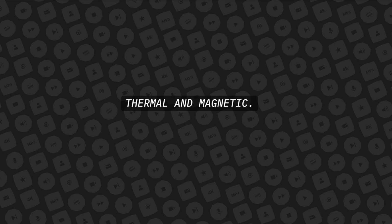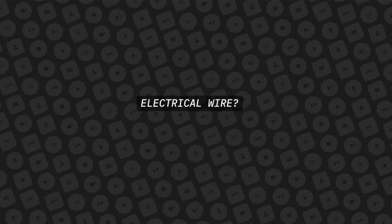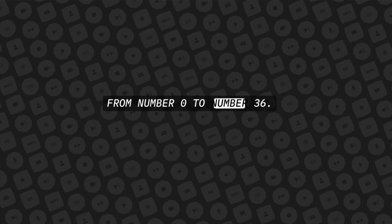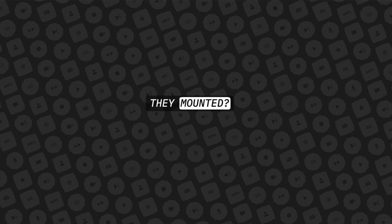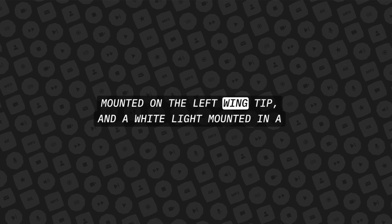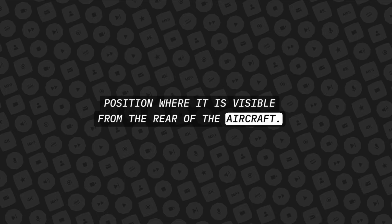Thermal and magnetic. What tool is used to measure the size of an unmarked electrical wire? A wire gauge can be used to measure wires ranging in size from number 0 to number 36. What are the colors of aircraft position lights and where are they mounted? A green light is mounted on the right wingtip, a red light is mounted on the left wingtip, and a white light mounted in a position where it is visible from the rear of the aircraft.